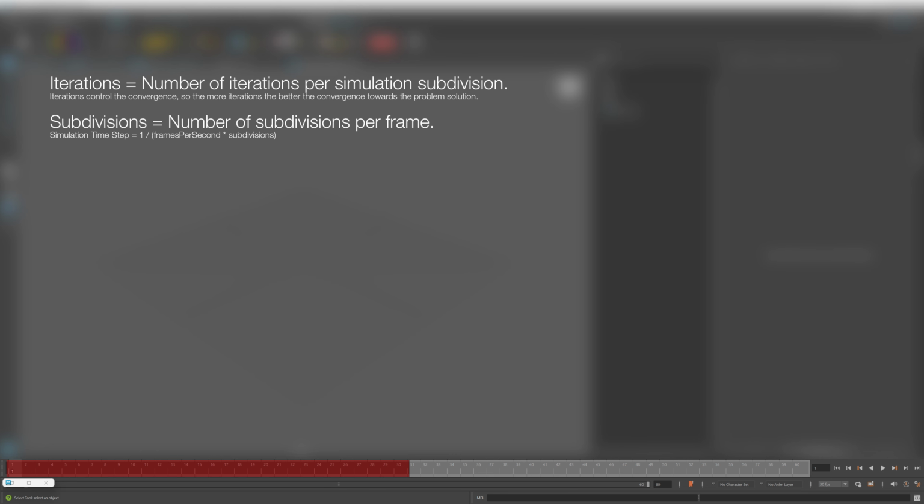If you have small or thin objects and fast motion, you need higher subdivisions to better sample the time to avoid objects interpenetrating. The number of subdivisions is also very important to capture fast oscillations. Time sampling must be smaller than the frequency of the oscillations, and the number of subdivisions is your friend in this case too. So in summary, any simulation error is relative to the simulation time step.